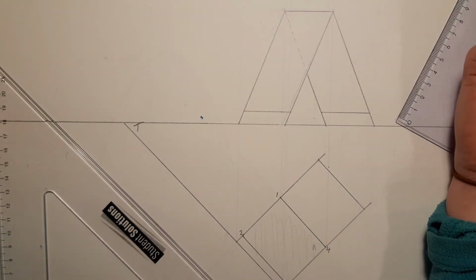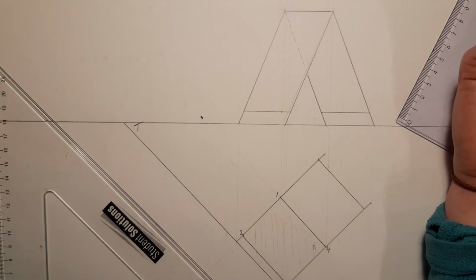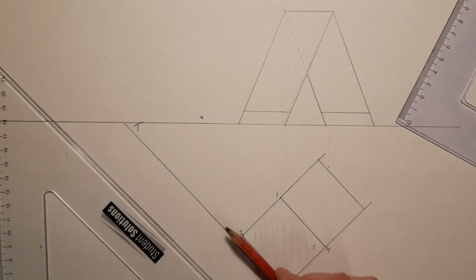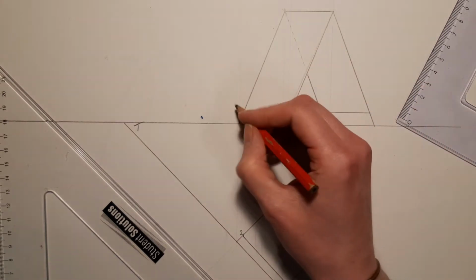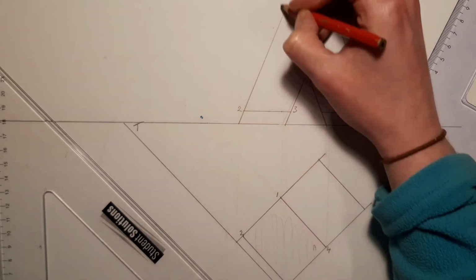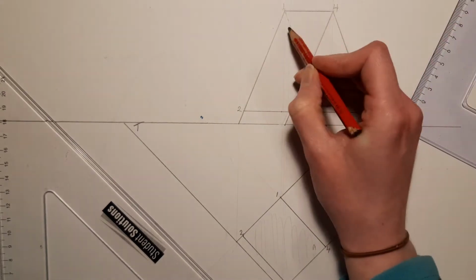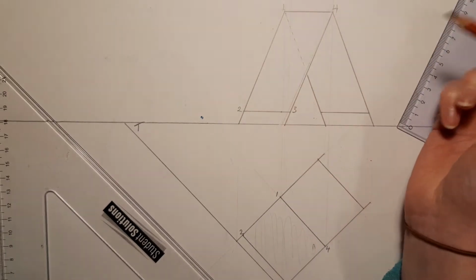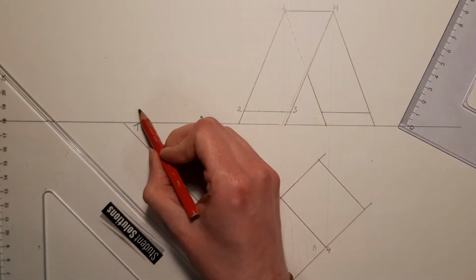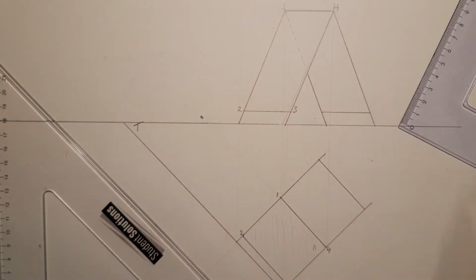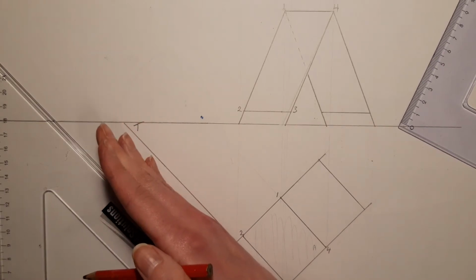But as I've always said to you, you're better off picking a higher point simply because of accuracy issues. If you choose the likes of 2 and 3, they're quite low. So I'll just reference these to the elevation 2, 3, 1, and 4. 1 and 4 are quite high. And as a result, it's easier for you to draw that line in afterwards. If you pick a low point, it's hard to get an accurate angle on it. So the higher up it is, the better it is. So with that in mind, I'm going to come parallel to the horizontal trace.